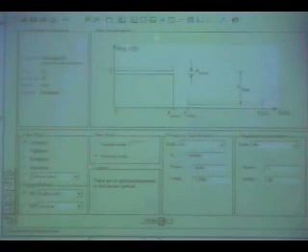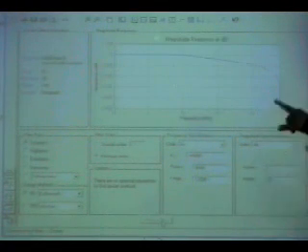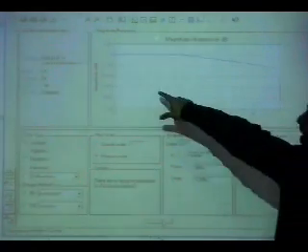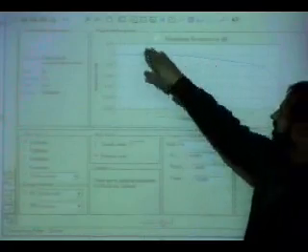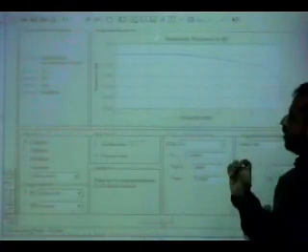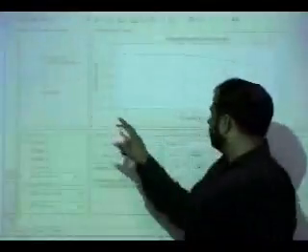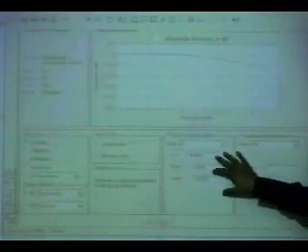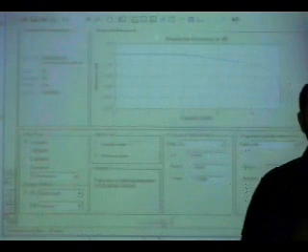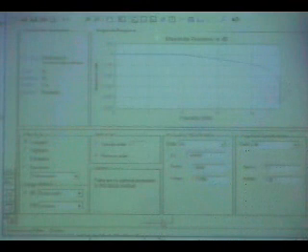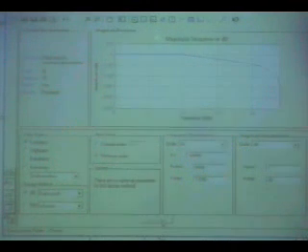So MATLAB comes back and tells you to look at the response. It's minus 500 dB, but it's very smooth. MATLAB tells you that for these specifications, it will take a 31st order IIR filter. 31st order means there will be 31 poles in the system. You can get B's and A's, but this is what MATLAB tells you.